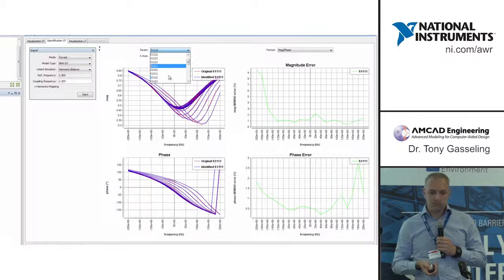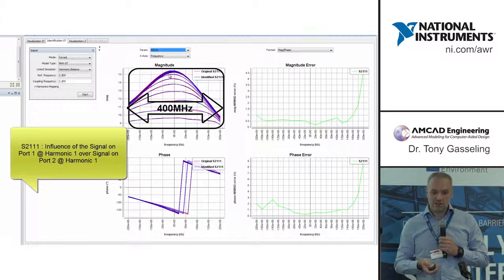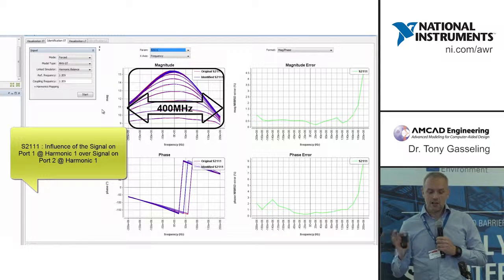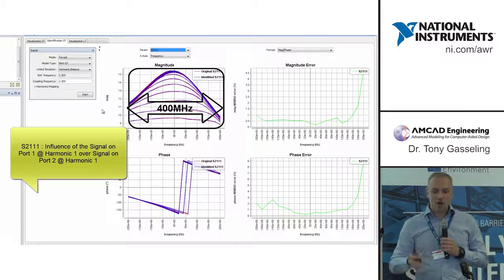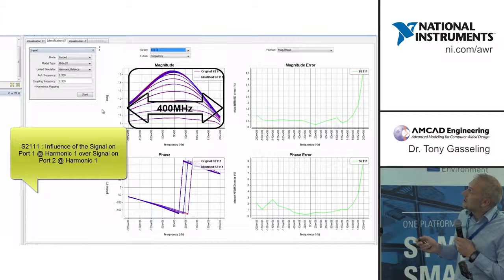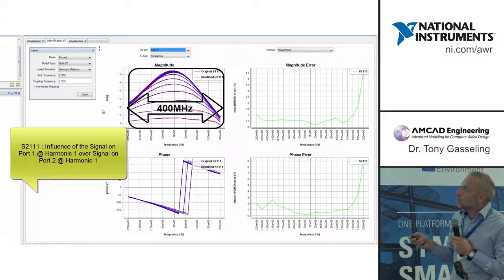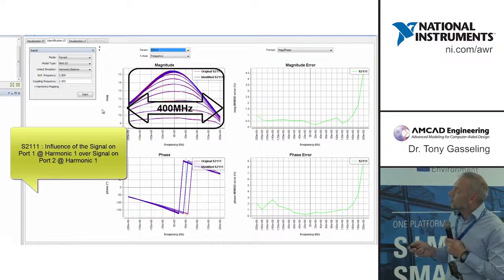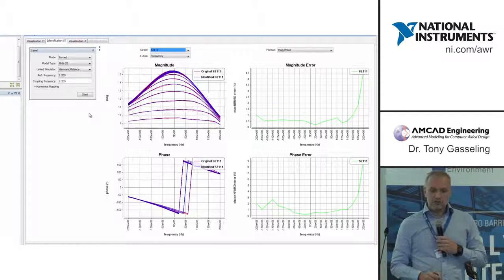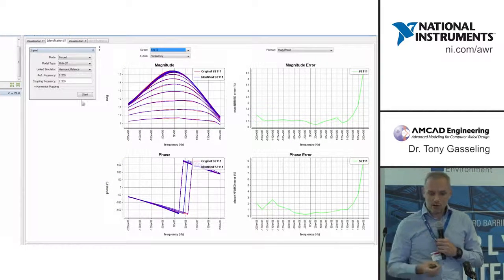And we can try to visualize what the different kernels are. So here it has been done only in a 400 megahertz bandwidth around the carrier. So for example, here we have, let's say in linear conditions, the S21. So this is the S21 in the RF bandwidth of interest. This is where we will use our modulated signals. Okay, so we can see that we have a good behavior here.